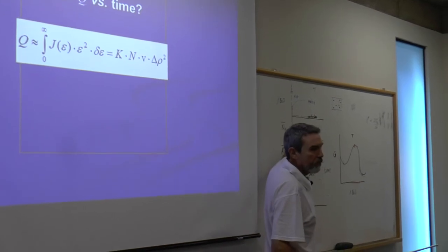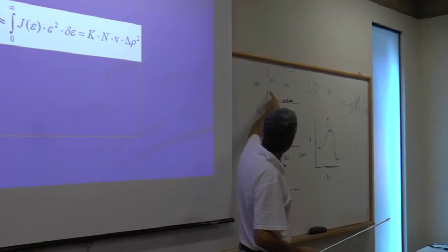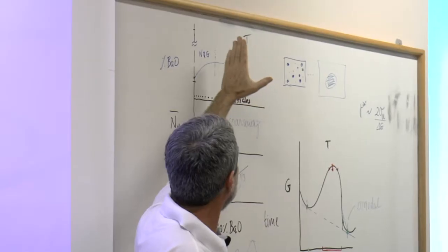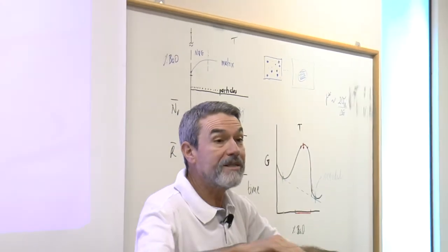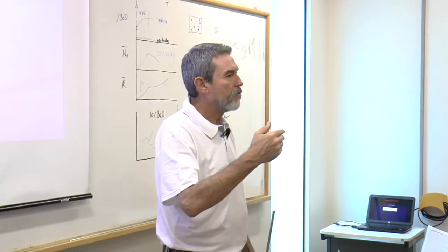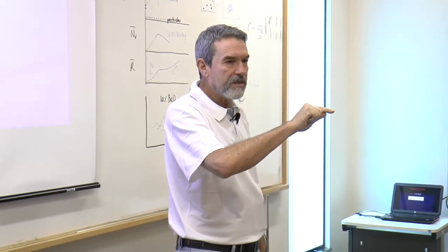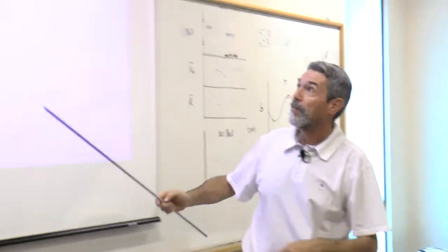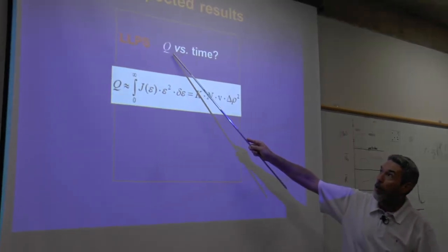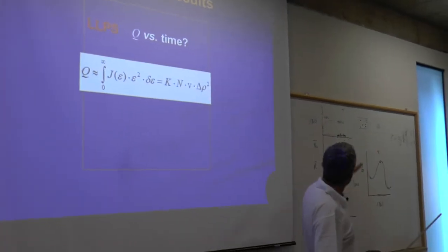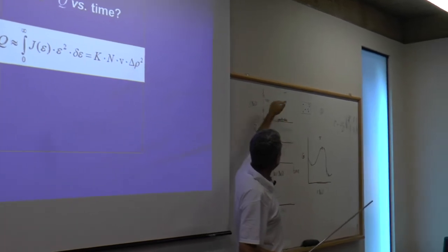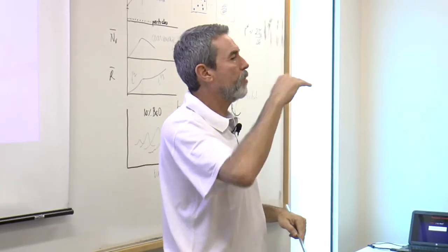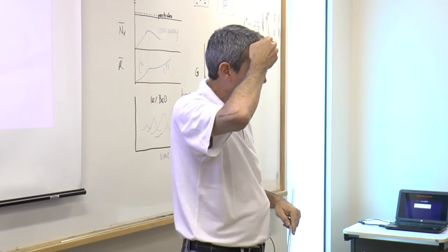This is a very slow process. So once you reach a constant value, it's because the process has stopped. It never stops, but the matrix phase has reached the binodal boundary. So this is a way to see what time it takes at a given temperature for a given composition for the phase separation process to reach the coarsening stage or to reach the binodal boundary.